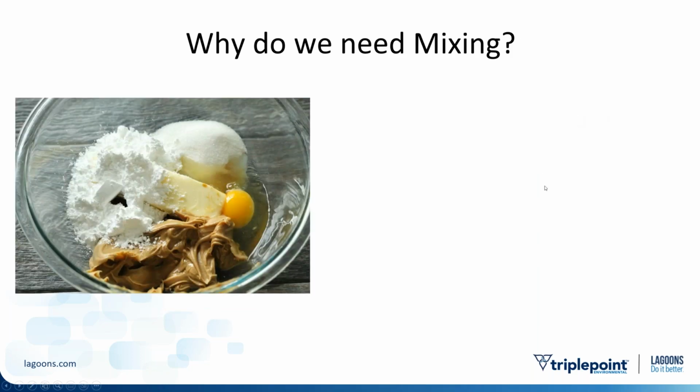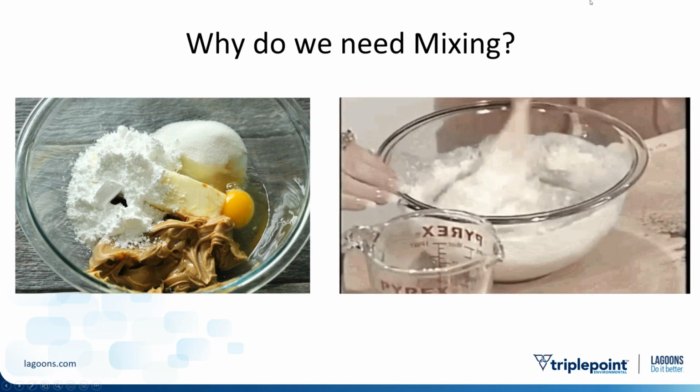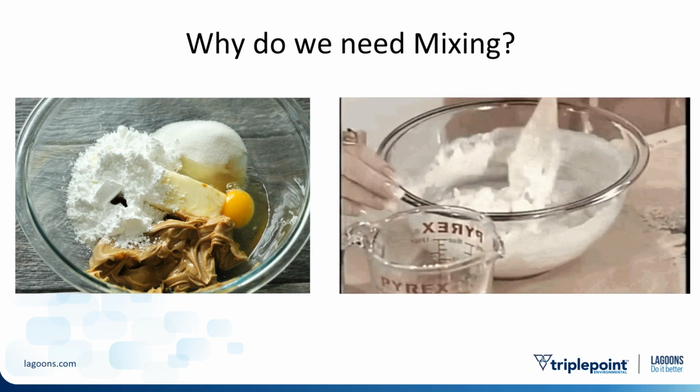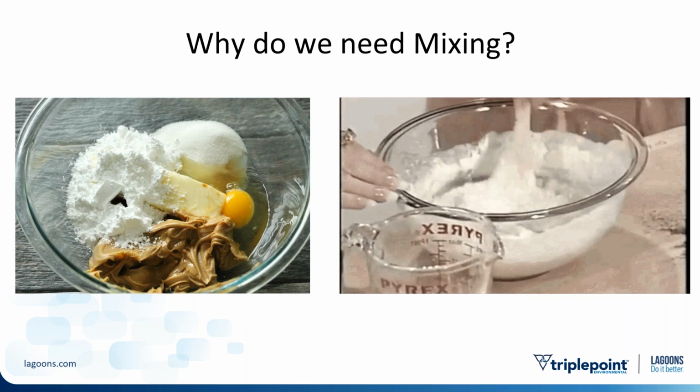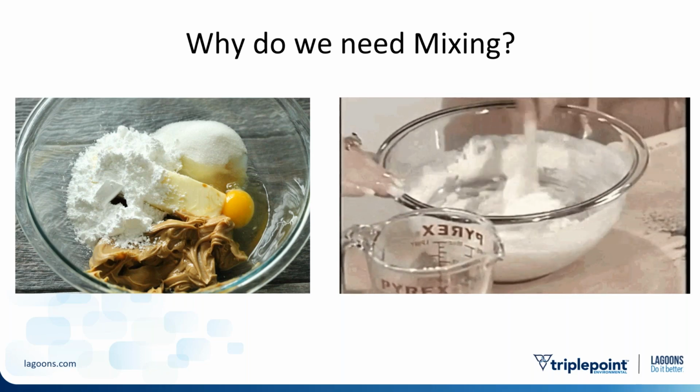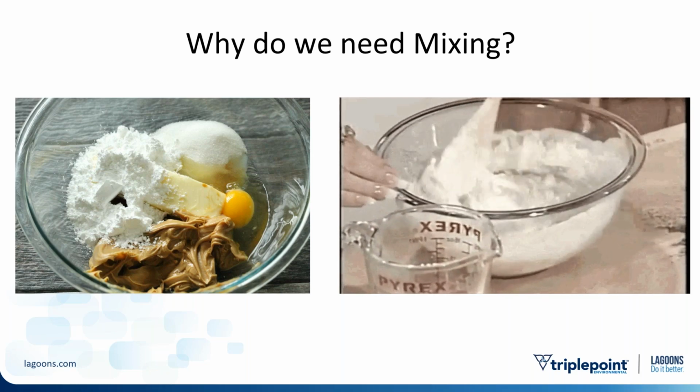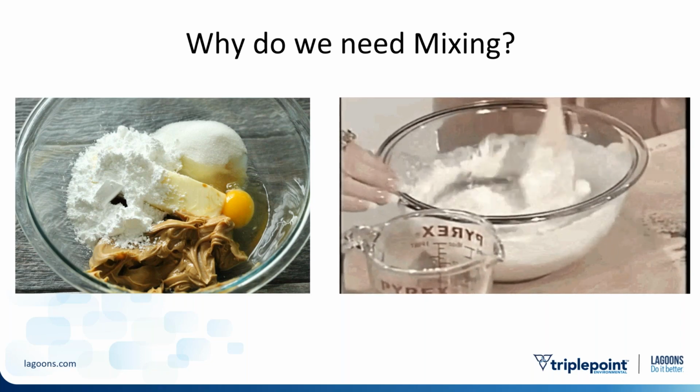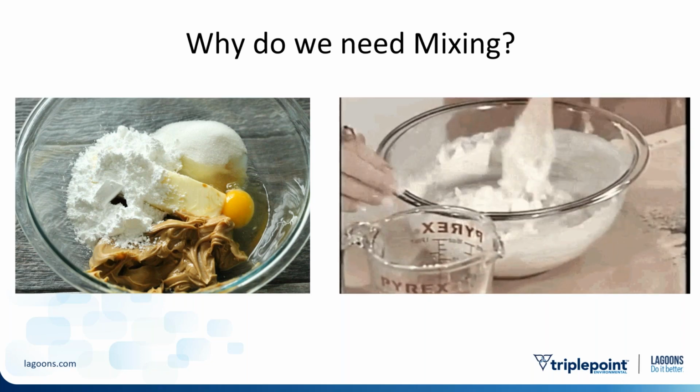And why do we need mixing? We need mixing because that is not a peanut butter cookie. That is not a cake. That is just a bunch of ingredients that are not well incorporated. No different than if we were to put a bubble in one end of the lagoon and waste in the other end of the lagoon, we're not going to get the treatment that we expect. What you have to do is mix it up so all these things are in contact with one another, and when we're able to do that, a certain reaction is allowed to take place. In this case, it might be a cake. In our case, obviously, what we're looking for is bacteria digestion.